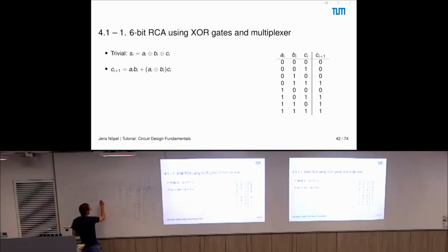So this is the right part, A XOR B, and this happens only if Cin is also true. And lucky us, if A and B is true, then the one here is also set, so this is already covered by the AB we've placed there before, so this realizes this functionality. So this is just one way to come to this function. There are also different ways, but that's how you could think of it.